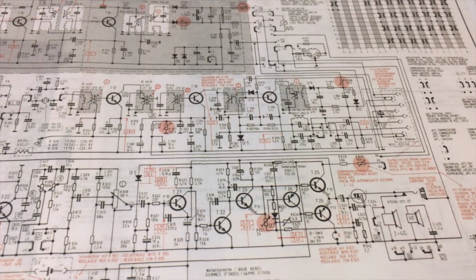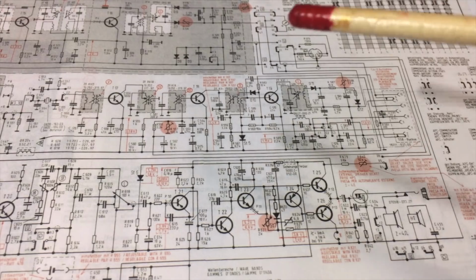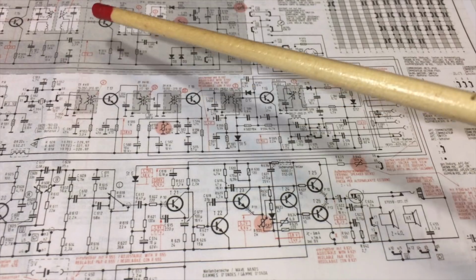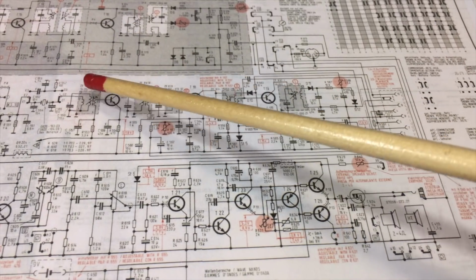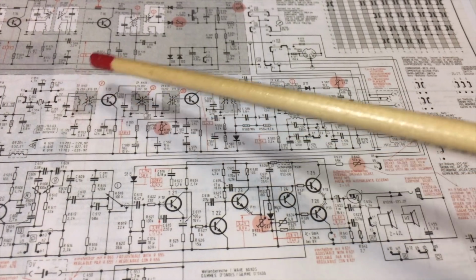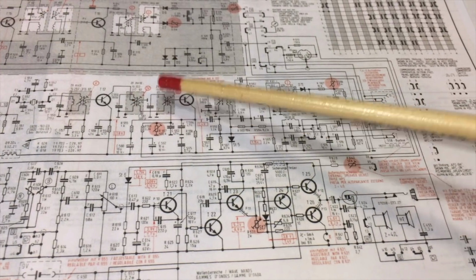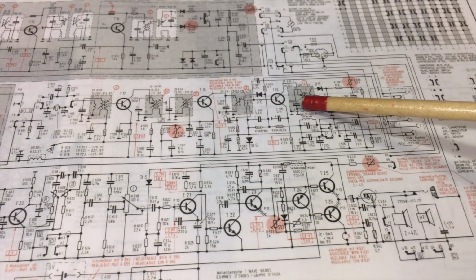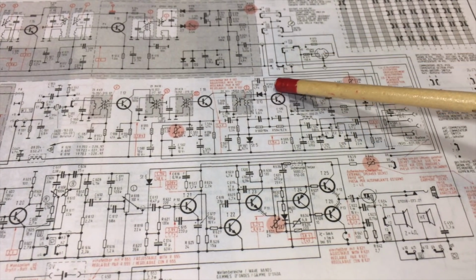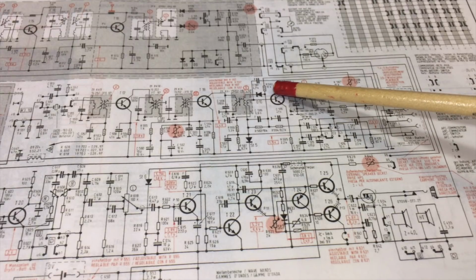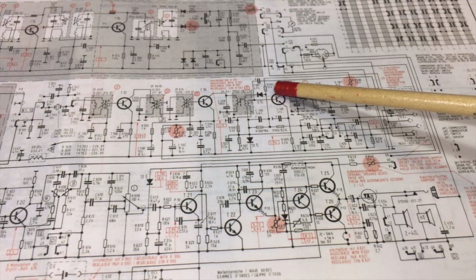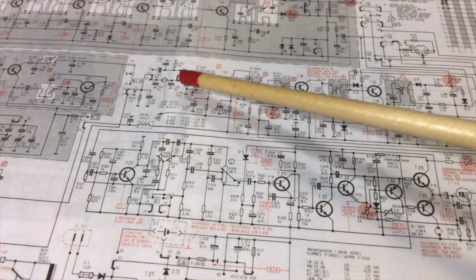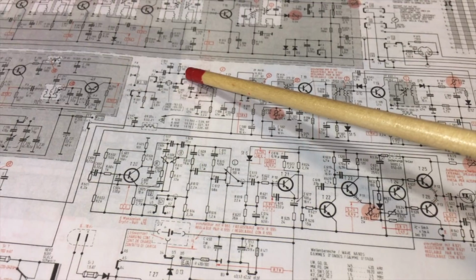So what have we actually achieved? Well, we have been feeding a signal into here. We've tuned that IF transformer. We've tuned those two. We've tuned that one. And we've tuned that one, because we are detecting the signal over here. Now, this has all been at 460 kilohertz, because that is the IF that we get coming in here.